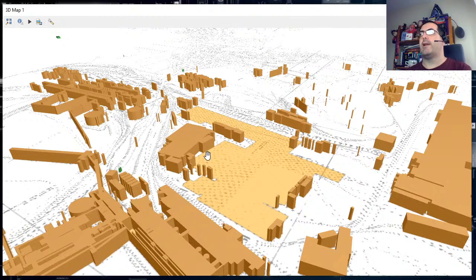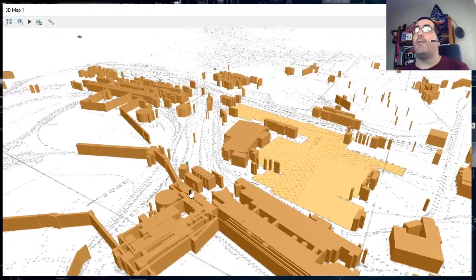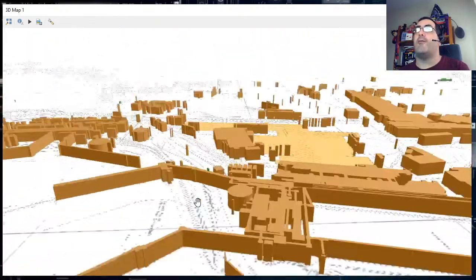When you're working very closely to other shapes, you're going to want to put your snapping on. You can see throughout what we've done so far, I can't bring the 2D one up when the 3D one's on screen, but throughout what we've done so far there's been a little magnet symbol on my toolbar, and that means snap to the nearest piece of geometry. And when you snap to things, if you've got the distance too close to each other, you might draw this but snap to this. So these may become joined on one tiny little joint down here somewhere that you wouldn't otherwise have noticed.